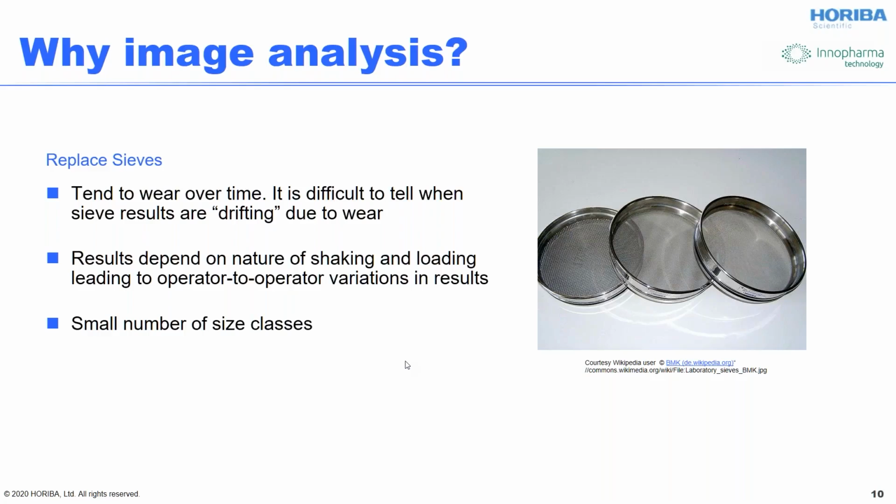Finally, there's a fairly high operation cost, because once you've put your particles on your sieves and spread it out over 10 sieves, you've got to wash dishes. You have to clean everything up, treating the screens, particularly the smaller, finer sieve meshes, reasonably carefully because they can get delicate. That contributes significantly to the measurement cost, both the time to clean and the time of measurement.